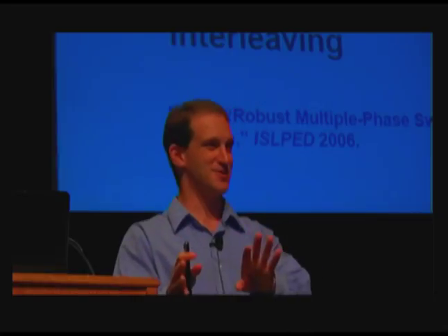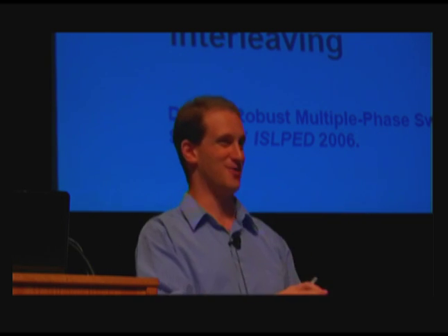Yeah, so it's a great question. Now, the thing to remember is that, especially for the topologies that I was talking about, so let's really look at something like this simple example where I just have two-phase interleaving, okay? So if I look at this example, then at any one time, one of these capacitors will be connected from V out to ground. The other one will be connected from V out to V in, okay? Now, this capacitor that's connected from V out to ground is a decoupling capacitor. Right? There's no difference between that and a normal decoupling capacitor, because after all a decoupling capacitor is a cap between V out and ground.